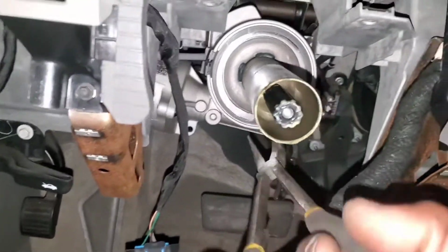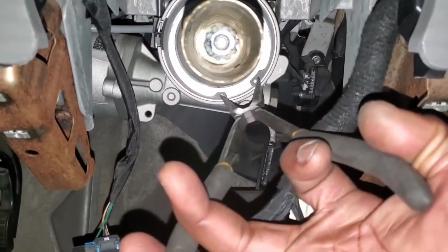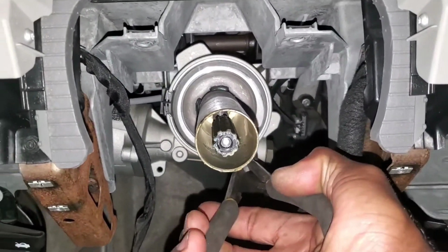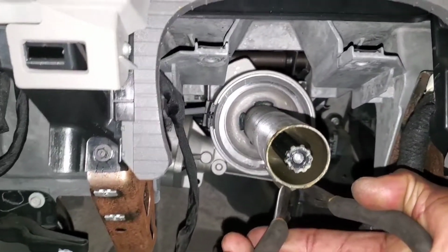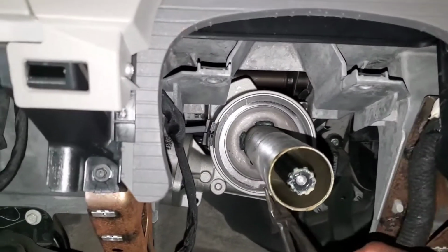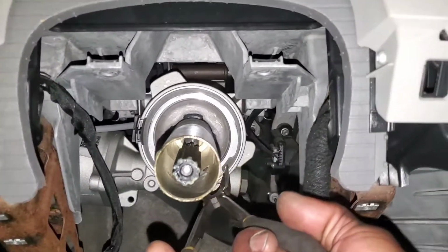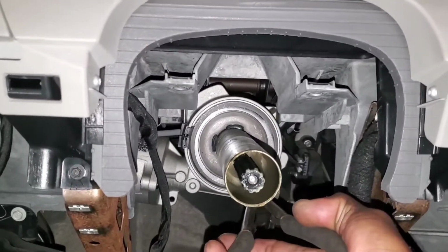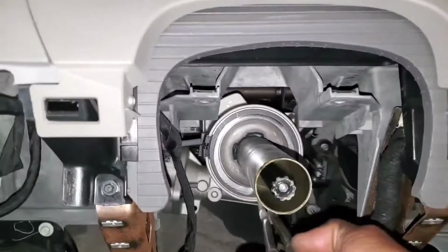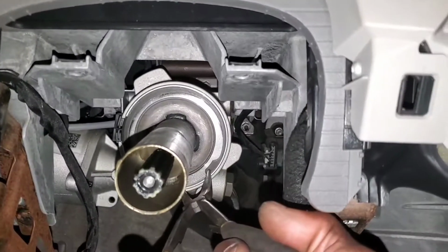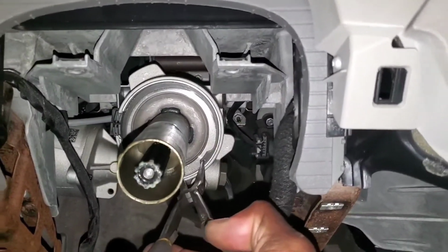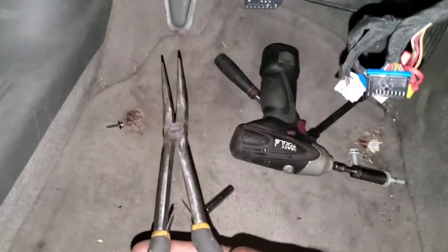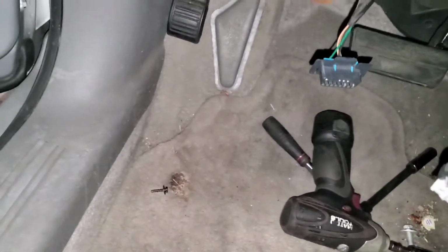Here's a hack that I was thinking about if you don't have needle nose snap ring pliers. Needle nose pliers will do. It's kind of in there, so safety glasses would be very, very well advised here. I'm going to get in on one side with this because snap rings have this habit. Once they've been sitting for a while, you can let them snap, and a lot of times the other side will come loose, but this one wants to fight me. So needle nose pliers, long ones like this, if you have them, will work.